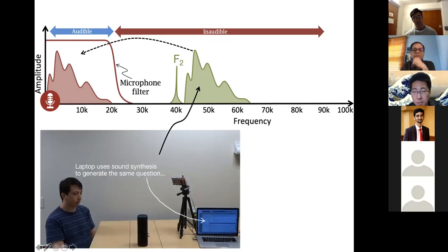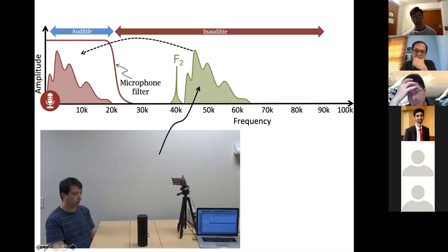Professor? Yes. Just for clarification, in this ideal model, we only need one F2, right? Just one frequency, and it helps all of the green. Correct. Because if you compare the F2 with every frequency in the Green Mountain, every frequency in the Green Mountain will shift by that frequency minus F2, right? 50K minus 40K will create a 10K. 60K minus 40K will create a signal at 20K.